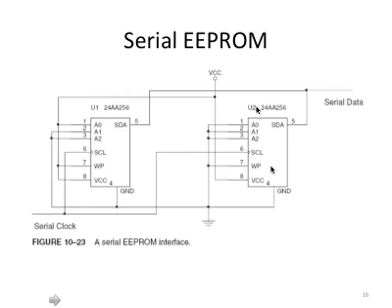In comparison, the chip on the right is connected in a way that all three address pins are connected to ground. So if you give a code based on the voltage, the logic level, this will be 1, 0, 0, and this will be 0, 0, 0. Now keep in mind, these values will later be used to identify the chip.